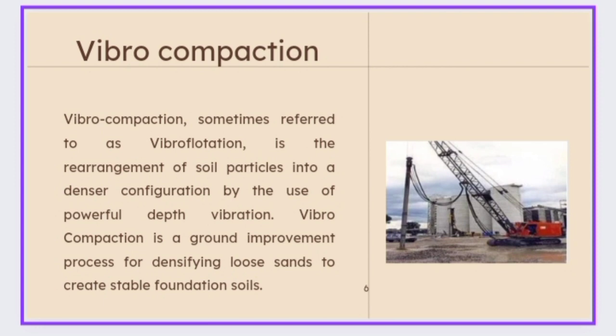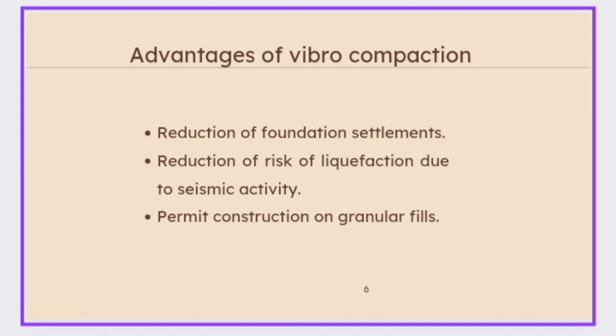The principle behind this is very simple. The advantages of the vibrocompaction method are that it reduces foundation settlements, the risk of liquefaction due to seismic activity is reduced, and it permits construction on granular fills also.